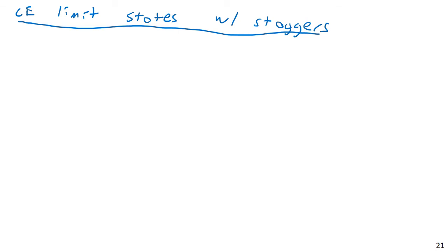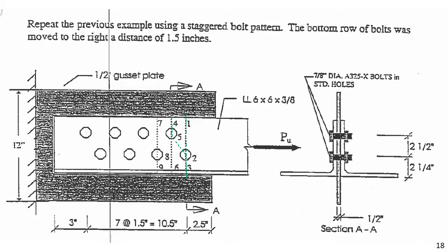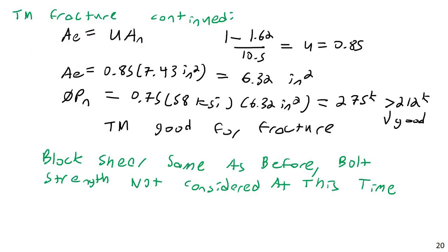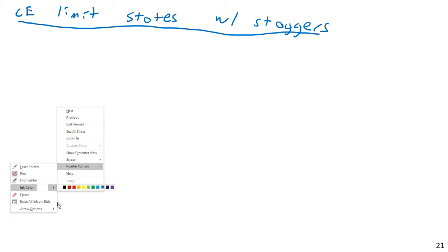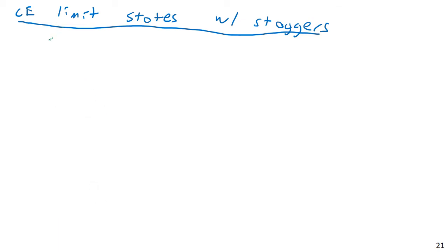Now this particular one, we don't need to worry about block shear because, again, you can sometimes have block shear with the gusset plate, but this particular one is so much larger dimensionally than our angle irons, and it's actually made of stronger material. So there is no conceivable way that this thing is going to fail in block shear before our angles do. Anyway, let's just go down the list though. But if you really want to be thorough, you could check it.